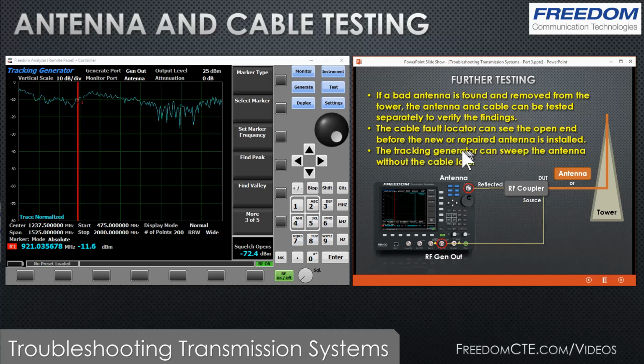And now you should have, using all three steps that we've covered so far, testing your electronics, testing your duplexer or RF network, testing your transmission lines and antenna, should be able to find the problem.